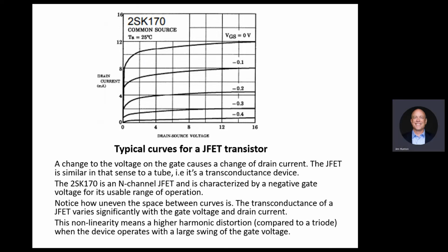So the effect of the drain source voltage is very minimal, which is actually a good thing in amplifiers. One less factor to worry about. And you get higher drain current as you move with the input signal. And the input signal, again, is negative. So we're repelling, we're limiting the current.